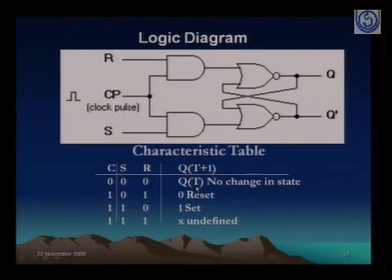That was the discussion when we said that after S moves to 0, the flip-flop remained in the set state. Similarly, for the reset case, we found that even if the value of R moves to 0, the flip-flop remained in the reset state. So that is what it means: no change in state. If it is 0 and 0, there is no change in state. Whether the clock occurs or does not occur does not matter in that case, so it can be 0 or 1 in that situation.